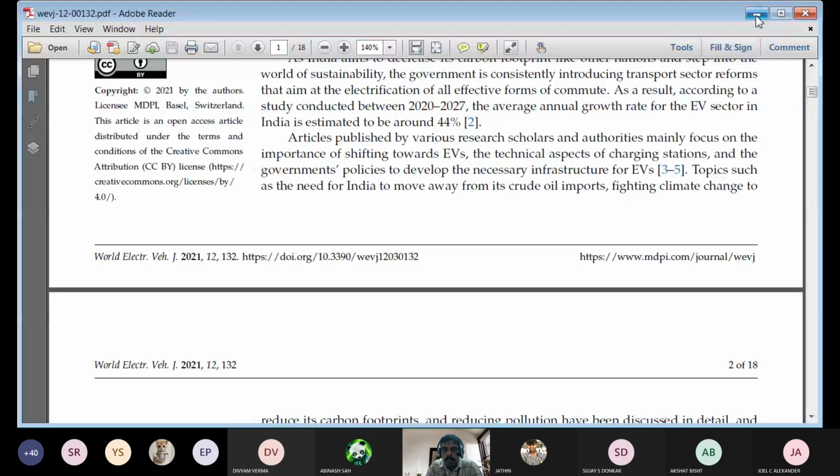Renewable energy has many demerits. It is diffuse in nature, that means per unit area we will get only a little. Solar itself, in a square meter we can expect 300 watt, 400 watt or 700 watt, less than 1000 watt. Wind also similarly, the density is very low. But anyway we will have to use it and increase its share. So we have power plants and some applications using this renewable energy.